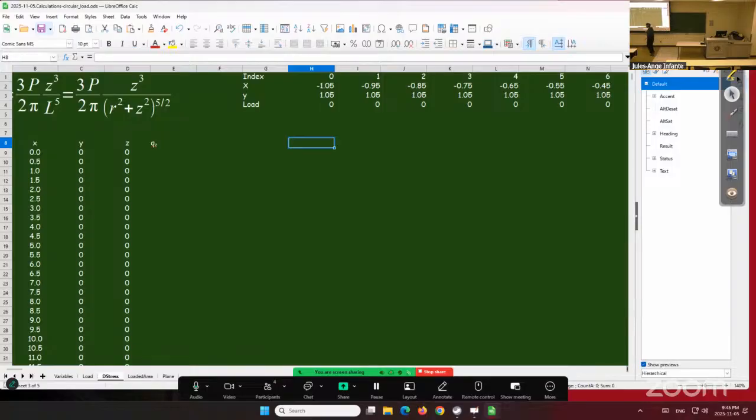So what I have here on this load, all those points there could just be extracted from the color scale of a bitmap image, for instance, that we created. You can have a complex geometry, you define your boundaries of your bitmap, and now you have a means of looping through it and create your initial stress. Little tricks of the trade.